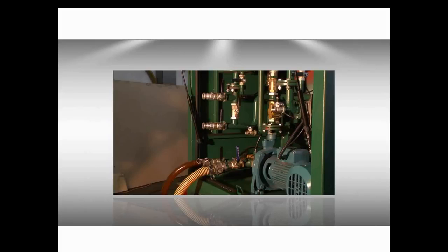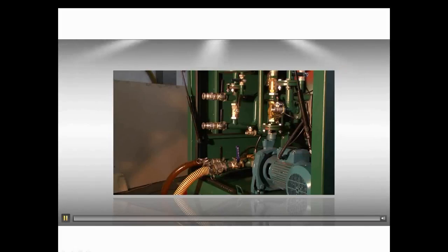For example, we have a 20 MVA transformer with 20,000 liters of oil inside. Approximate acidity is 0.1. To do the job with a regeneration plant, it takes about 5 days. So initial acidity is 0.1 in oil and in windings. Oil comes to the plant, passes through the regeneration cycle and goes back to the transformer.